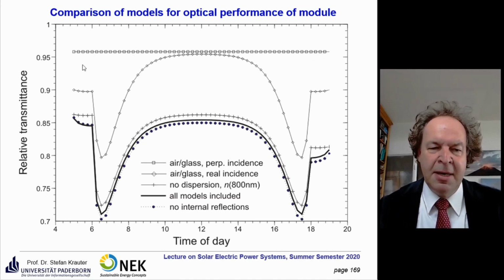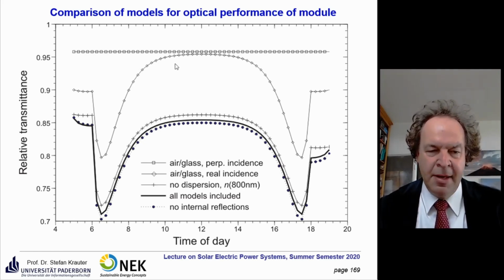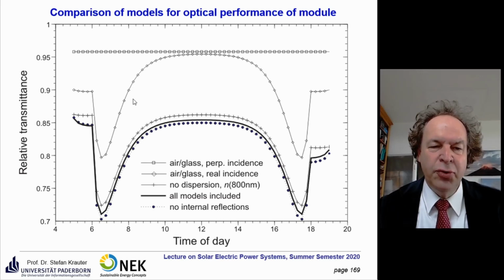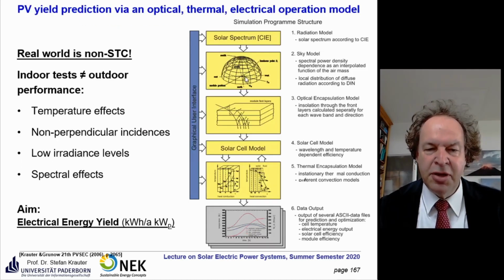And this may lead to inaccurate simulations of the actual performance of the PV module. If you make it a bit more accurate and consider the actual incidence angle of diffuse and direct irradiance, so we made a model here, not only considering direct irradiance but considering all, because even on a very clear day, 30% of the incoming irradiance is diffuse irradiance.